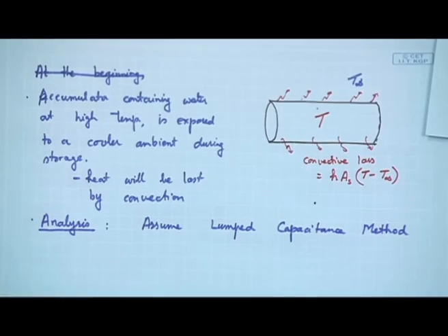In the lumped capacitance method in heat transfer in transient analysis, we assume that the entire body which is being cooled is at a uniform temperature, right. And if you recall, that happens when the Biot number is much less than 1, and so on, okay, which also indirectly means that either the heat transfer coefficient on the outer surface is very low or the thermal conductivity of the material is very high. Clear? So, you can use lumped capacitance under these conditions.